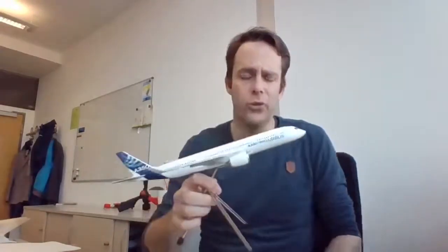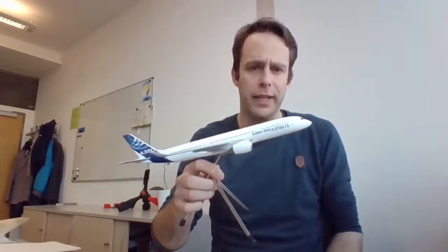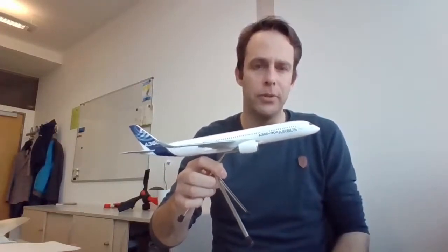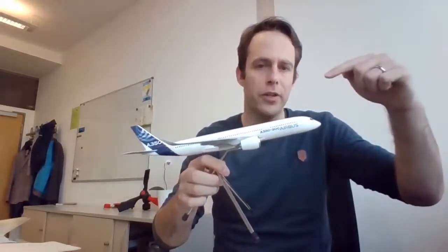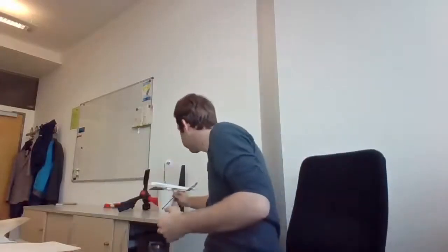So overshoot is only valid for oscillating systems. Why is this so important? If you design control systems for an aircraft and the pilot pulls the stick and wants to go here with the nose, and it's going to do like this, there's too much overshoot. So this is an important parameter to evaluate your system.